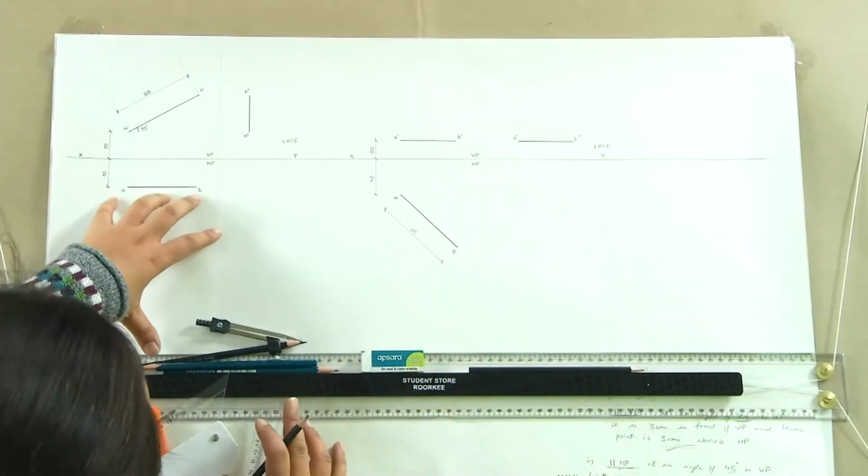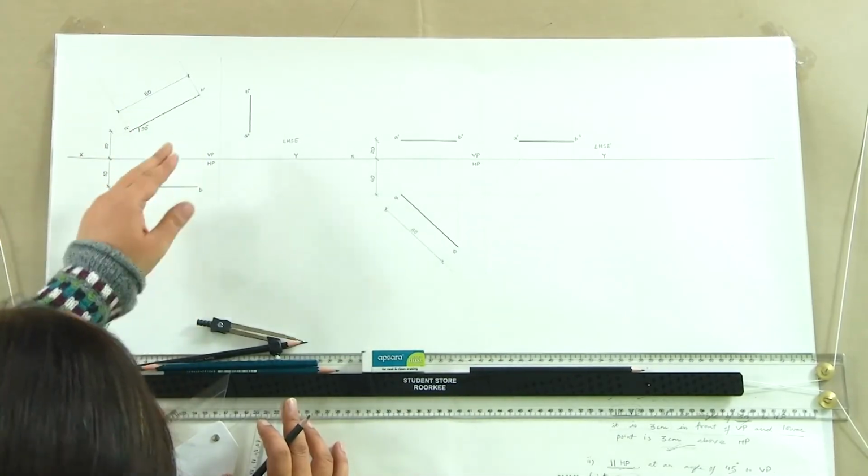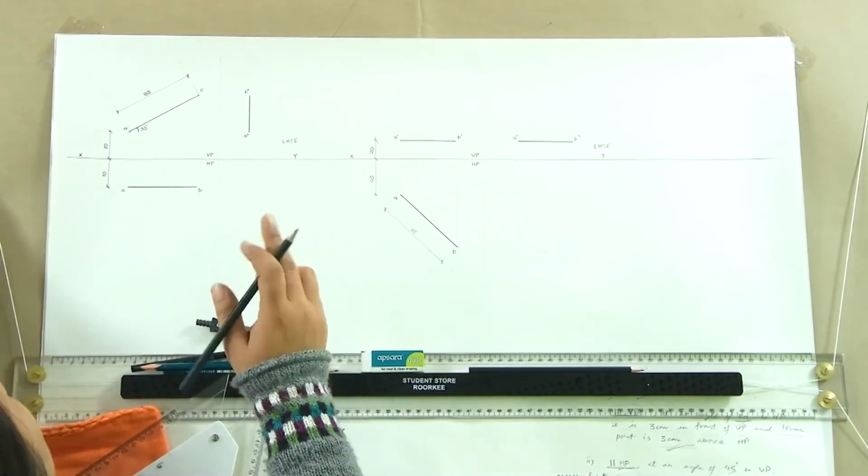Now, one thing which I should emphasize, and you should be very careful about this, is as you see when I draw all these drawings, there is a distinct thickness to each type of line. Always, I will repeat, your sheets look very good when you vary the thickness. Even if you start working on CAD, you will be required to select the correct thicknesses, and that is the essence of a good drawing.